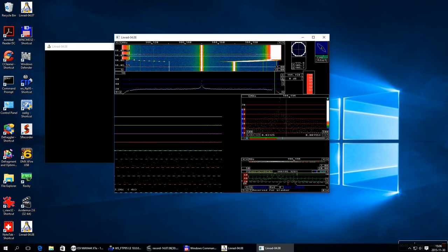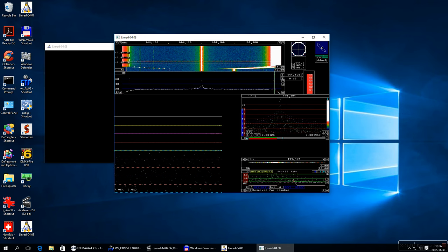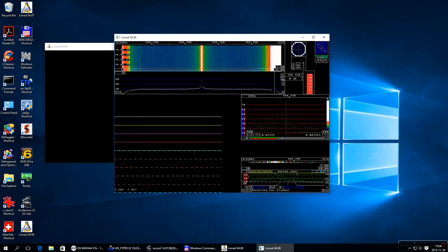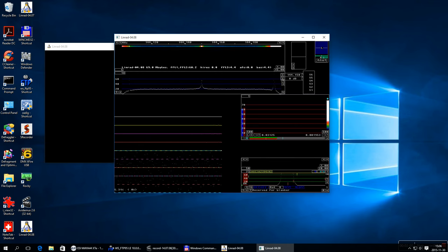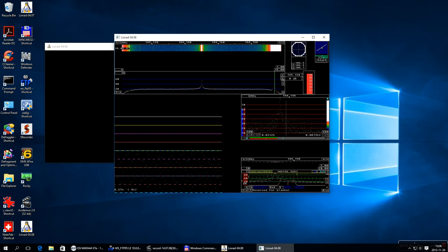So what you can do is have a test signal that is approximately equal in amplitude in both your antennas, but for which you know what is the proper polarization indication. So if you get it wrong like this, then just exit and then go back and look at the signal. Now it's correct. Now the blanker will work.